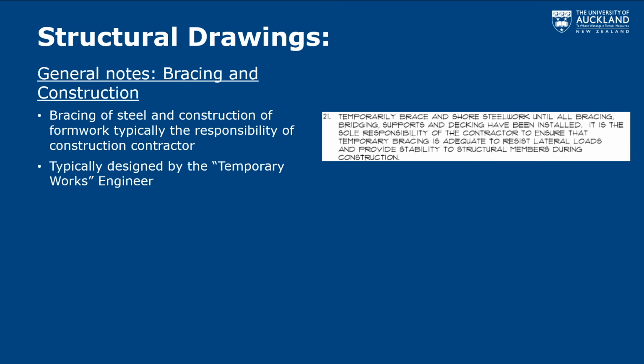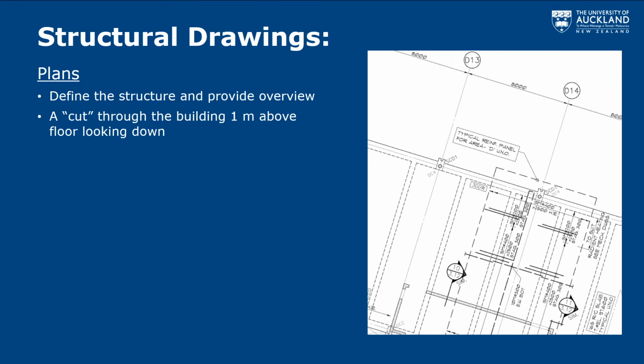So moving on to structural drawings and the actual drawing part. What most people think of when they think of drawings is building plans or the blueprints. And so I figure we'd just give an overview definition of what we mean when we refer to a building plan. Pretend that you're standing on the floor of a building, and you've cut the building all the way parallel to the floor at 1 meter above it, and you're looking straight down. And that's what the building plan is representing.